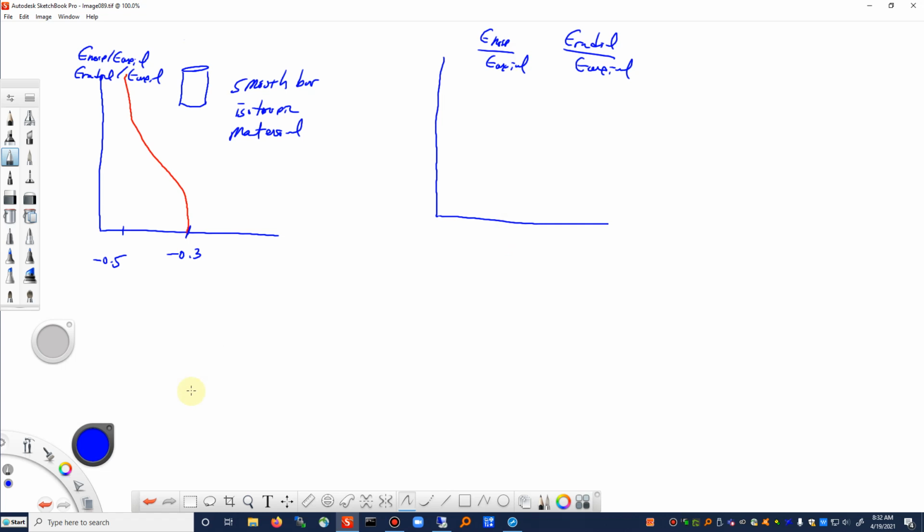So if I were to take these and let's see, the hoop stress over the hoop strain over the axial strain, that ratio should be reduced in magnitude. Okay, so I'm going to say maybe it is minus 0.2. Depends on the severity of the notch. We end up with a tensile stress in the hoop direction, which counteracts the contraction that we would ordinarily see due to Poisson's ratio.